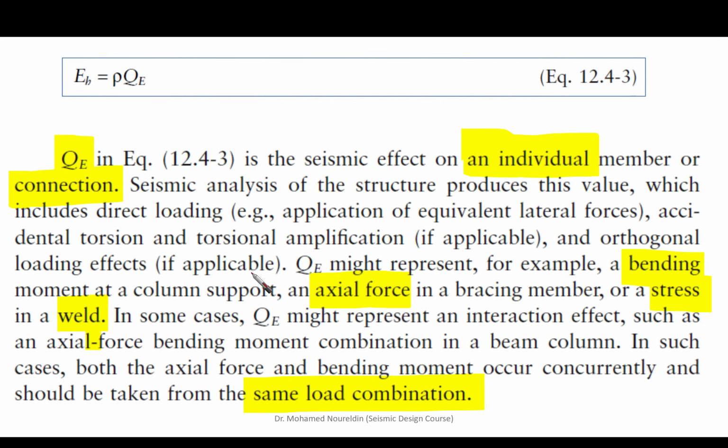Now let's go to the next one. EH should take, as we said, this rho, which is the redundancy factor, and QE. What is QE? It is the seismic effect on an individual member or connection. We are talking about QE, the individual element or connection,